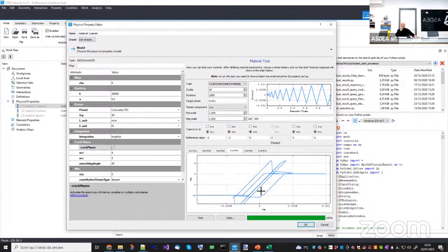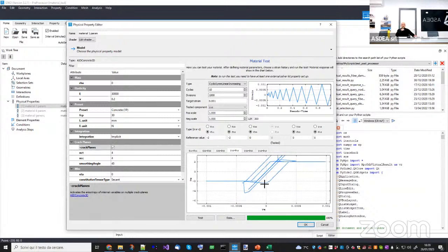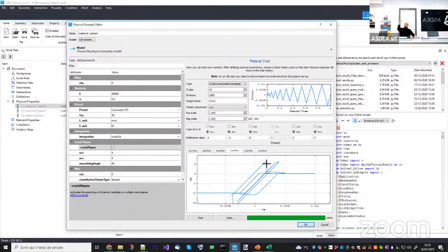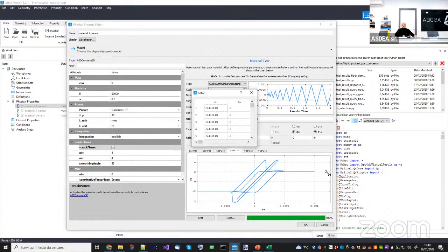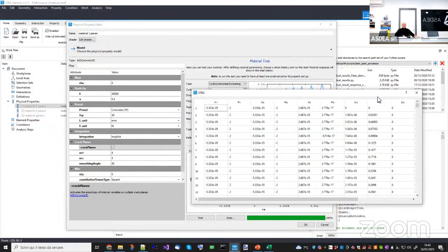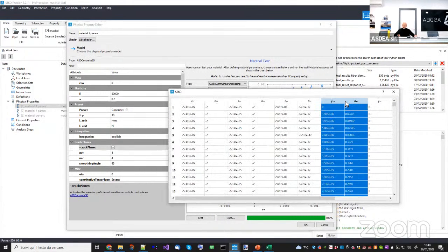Now you can already see a difference. Okay, so I go up to 4.5 here, strain hardening. I go down here, reach the same value, strain hardening. Then I have softening up to 2.5. But when I load here, I reach the same point. So I have to put softening also in the other direction. I have to open a crack in the other direction. Then I go in softening and then I reach the previous value. Okay. So if I compare this one with the previous, you will soon see what's the difference.